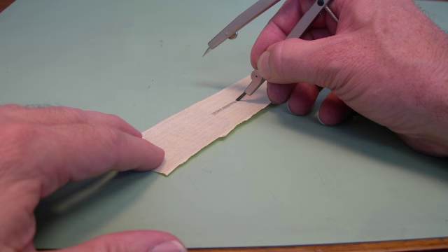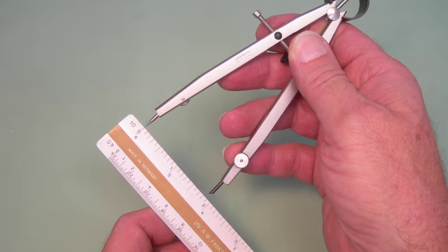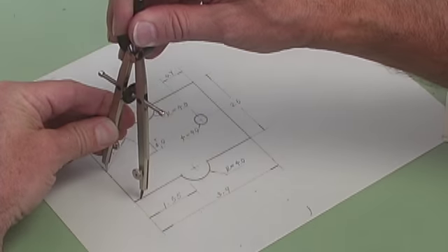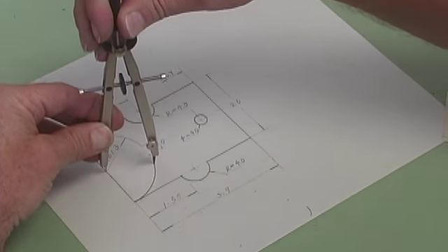You can make the chiseled point by using a fine sandpaper. To draw a circle or an arc, first spread the arms apart using the adjusting screw so that the tips are the exact distance of the radius. Always finish adjusting the spring-loaded hinge in the direction that is against the force of the spring. This keeps the spring from causing the adjusting threads to slip. Slightly tilt the compass in the direction of rotation as you draw.